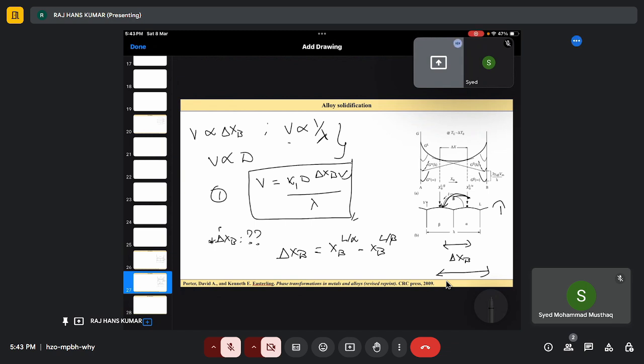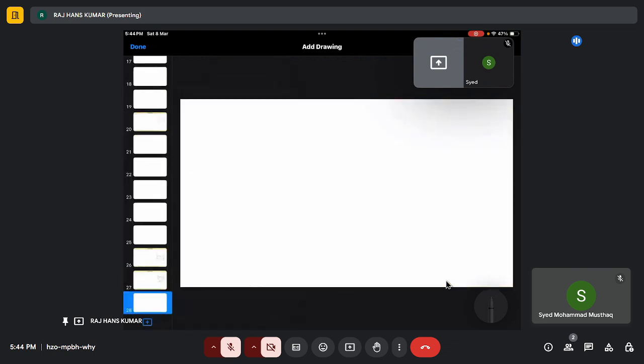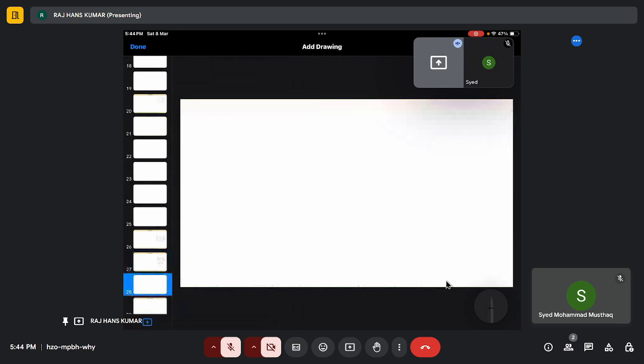And also at lambda equals to lambda star, that means the maximum allowed distance or the thickness of alpha plus beta for which our delta g equals to 0, that means the delta x equals to also 0. Right? Taking that in mind, we can again write this empirical relation. So delta x will be equals to delta x naught when lambda equals to infinite.